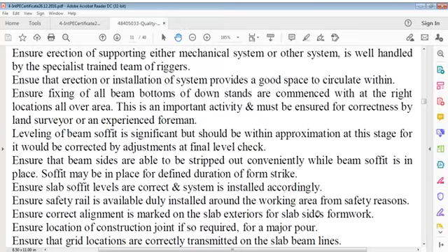Now, for the system that we are going to pour, we have to make sure that everything is perfect, everything is fine. The supporting system must be certified by yourself or by the manufacturer who provided this material and design. Erection of the system must be good, and there shall be space around, below and on the sides for your people to move. Of course, that's a grid system. Generally, grids of 1.2 to 2.4 meters are considered safe for that portion.